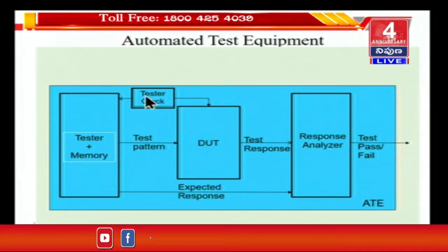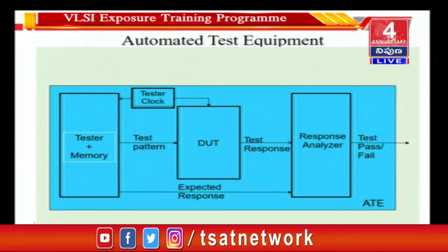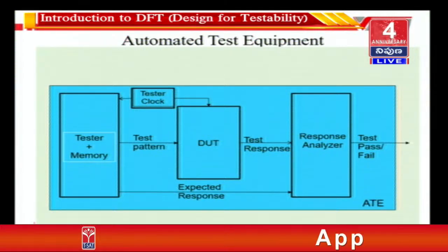And of course you have a tester clock also, which runs at some frequency, but typically testers do not run at the same frequency at which the device could run, because the device could be of a newer technology. The first thing that somebody makes of a new technology is a device, okay. The testers will come much later, okay. So the testers may not have the same frequency of operation as the device.